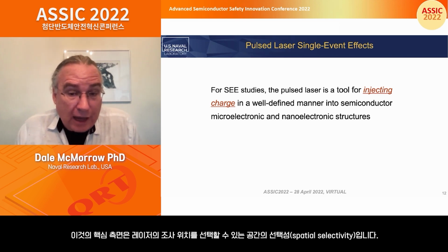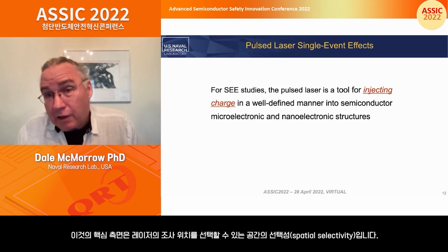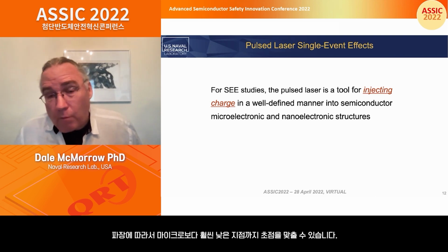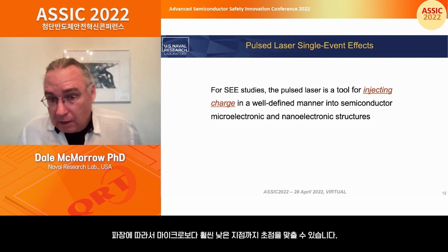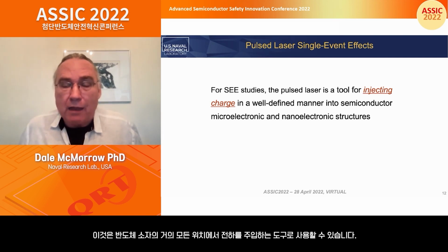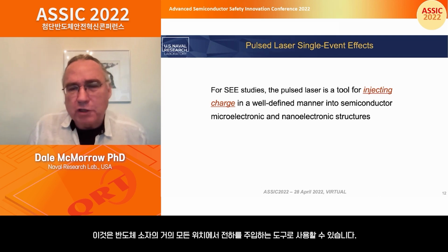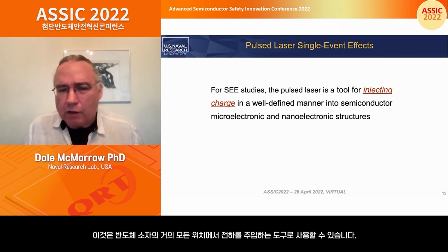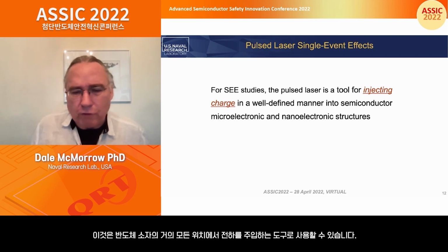The key aspect of this is spatial selectivity. You can focus down to a spot, depending on the wavelength, well below a micron. And you can use that as a tool for injecting charge pretty much anywhere in a semiconductor device that you can gain access to.